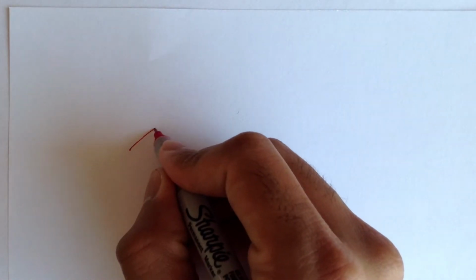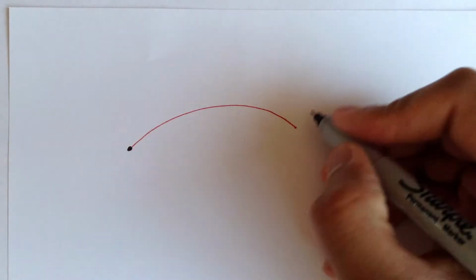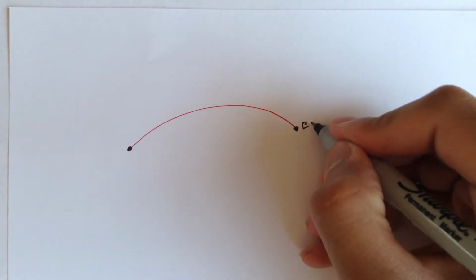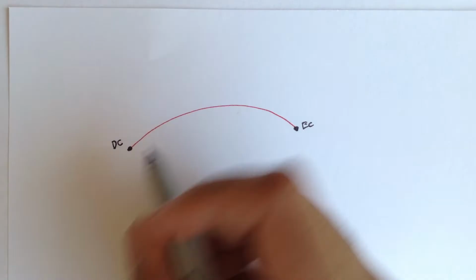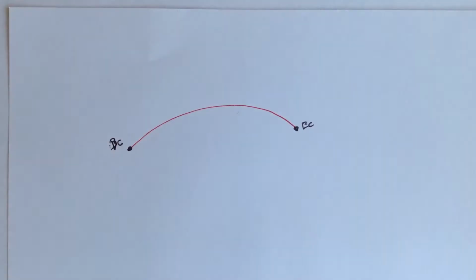Alright, so in this video we're going to talk about the external distance and the middle ordinate. These are two more parameters we can use when we're designing horizontal curves. So if we had this curve, and remember on this curve where the curve starts, this is the BC and this is the EC. BC stands for beginning of curve and EC stands for end of curve, right?